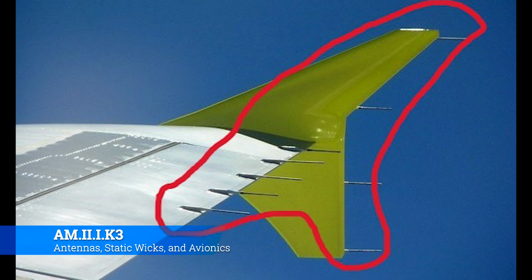That's how dangerous this can be. And static wicks provide a way to channel all those electrons out of the body and back into the atmosphere. Now, the way they do it is that they have a small, almost broom-like construction at the very tip of it. Some of the older ones are these graphite, almost like yarn hanging out of it. The more modern ones are still stiff, so they maintain their edge as they fly, and they don't fall apart on you or anything.